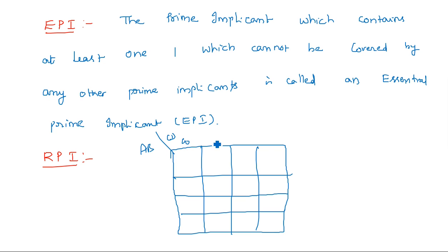Okay, 0 0 0 1 1 1 1 0 0 0 0 1 1 1 1 0. Now for example, consider 4 ones like this, and one here, one here, one here, one here. Now by seeing this, but first we will map these four because these four are at the center and they are adjacent together. So what do you mean by this? This is a prime implicant.